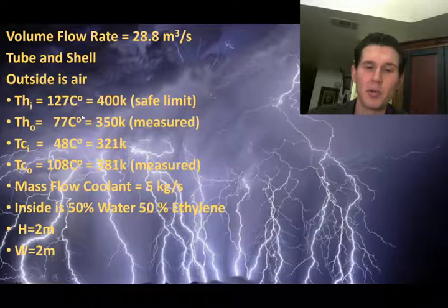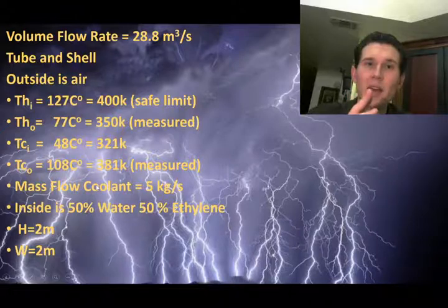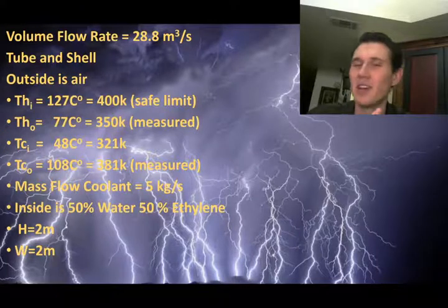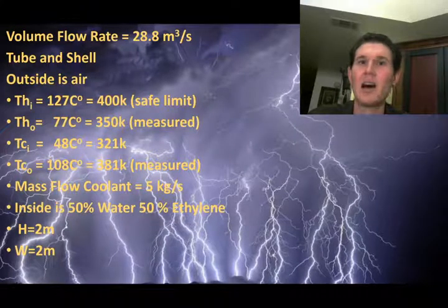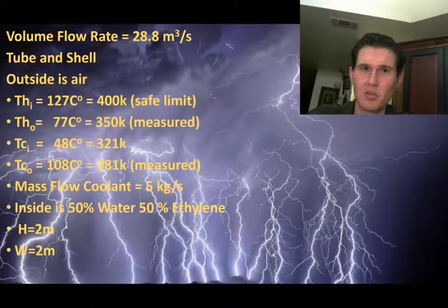And remember, we convert all these to Kelvin. Don't make the mistake of leaving them in Celsius. It is a mistake. You will have problems in heat transfer if you leave your temperatures in Celsius. I know it's easy. I know it makes a lot of sense, but it's really easy to make a mistake when you're putting stuff in Celsius instead of Kelvin.